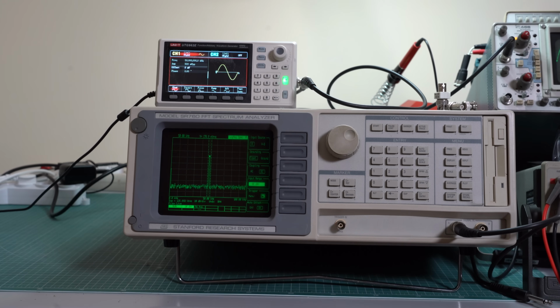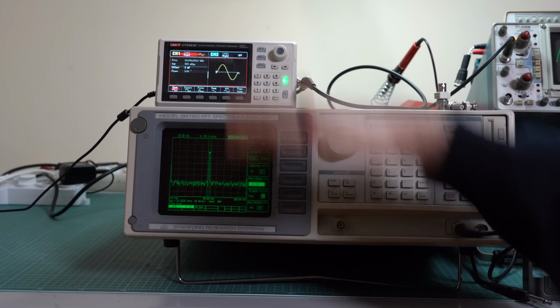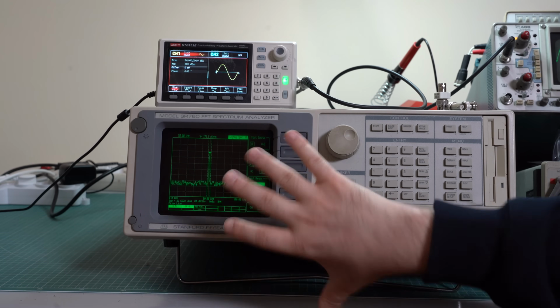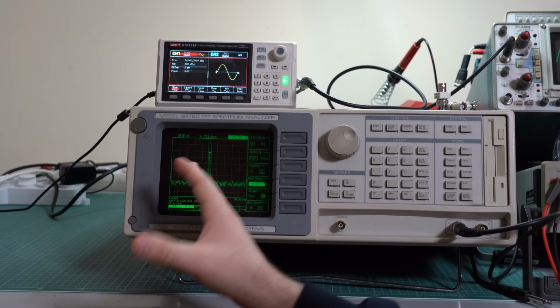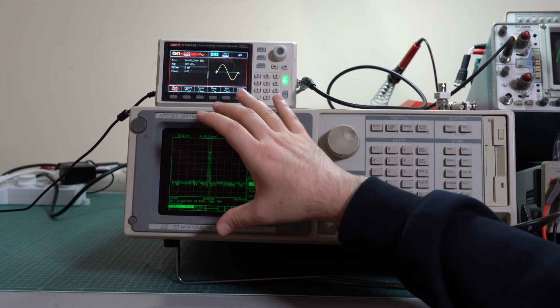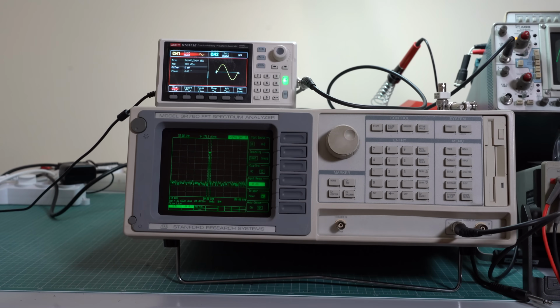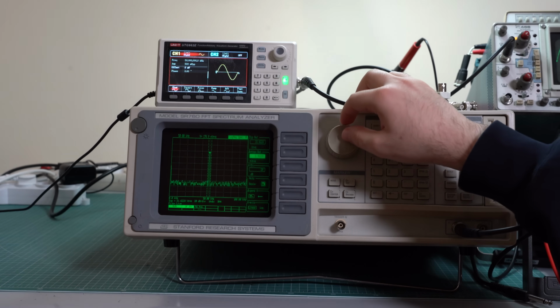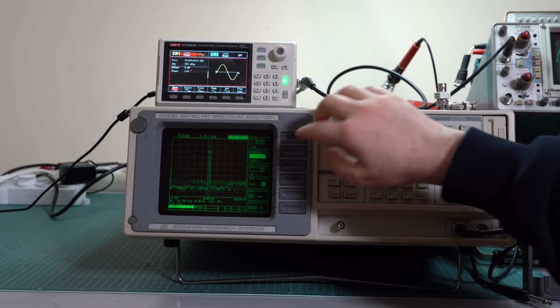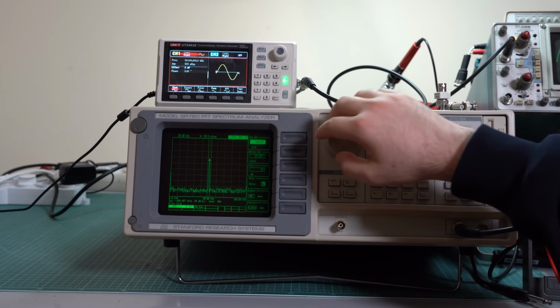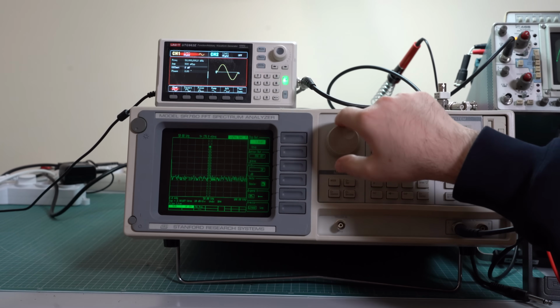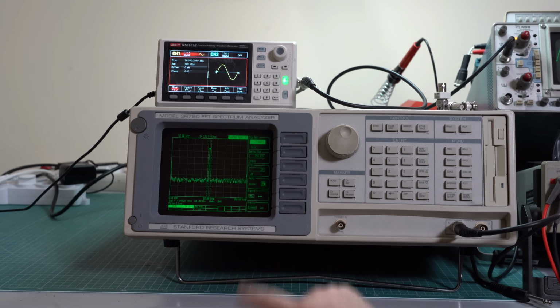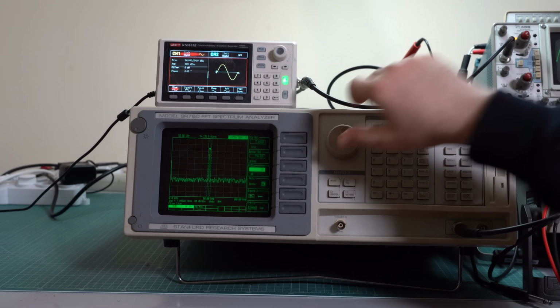What you can also do here is auto scale it, or you can set the scale manually so that you get a reasonable range between the minimum amplitude and the maximum amplitude that you see here, so that the signal has the right height on the screen. This can also be set manually by pressing the scale menu, and as you can see, you can set here the bottom reference, which is the lower level, or the top reference, which is the upper level, but in this case they just move in sync, and that's because you have a fixed amount of decibels per division here, which is something that you can also set.